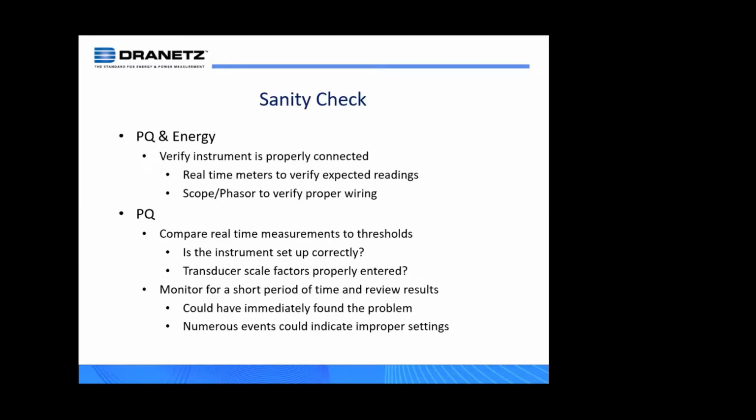For power quality, you're basically going to do the same thing. You want to verify the numbers are valid. You want to verify you don't have reverse polarity and things of that nature. Another common thing that we see is make sure that what's called the transducer scale factors, some people call them multipliers, some people call them scale factors. You'll hear different terms. You want to make sure that they're set correctly. If they're not, then it's going to fail the sanity check, because you're going to see current readings that are not what you expect. So those are things that you want to verify.